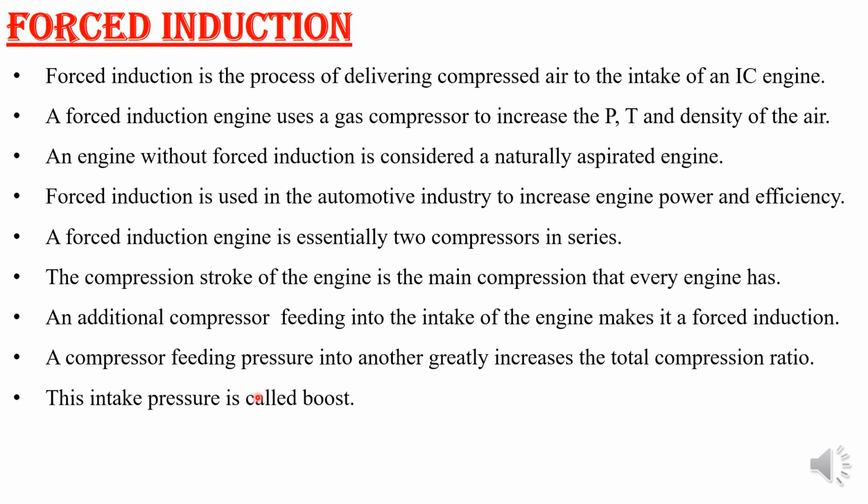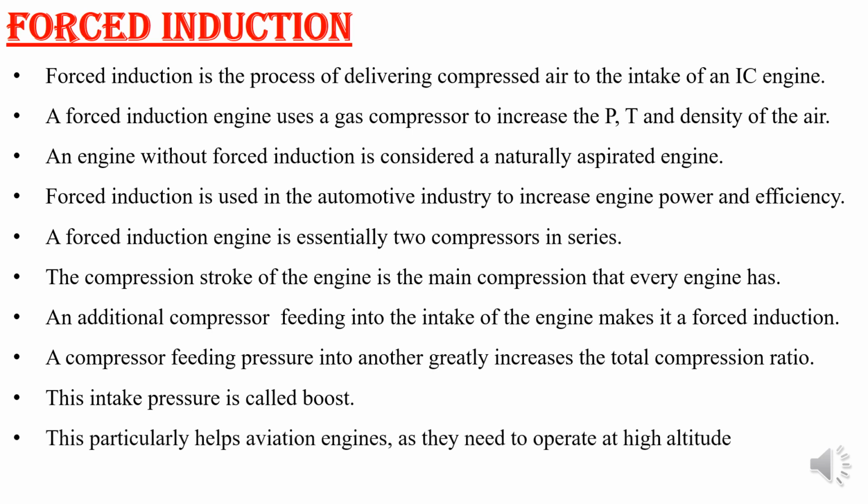Remember, the intake pressure which is higher than your normal atmospheric pressure is known as boost pressure. We are boosting that pressure so that the amount of air inside the cylinder increases. Especially in aviation engines, it helps when they have to operate at high altitude. So this boost pressure helps greatly in the aviation industry.